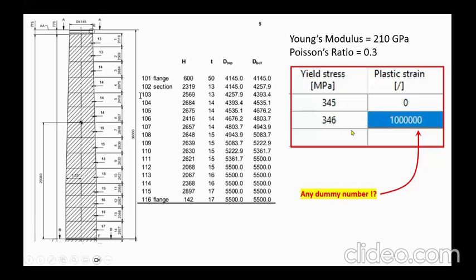He's arguing that because of the convergence issues that you may have with elastic fully plastic, he's giving a very slight tilt to that fully plastic slope, basically. And he's using a million, I use a million. That's irrelevant. This number is a dummy number.